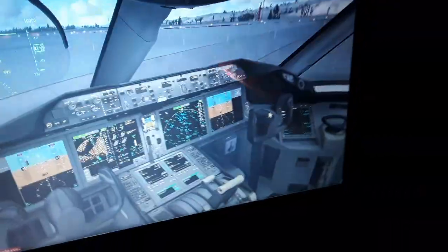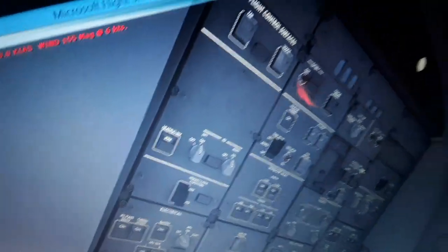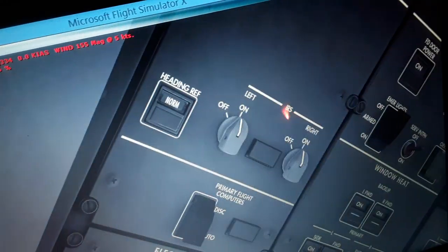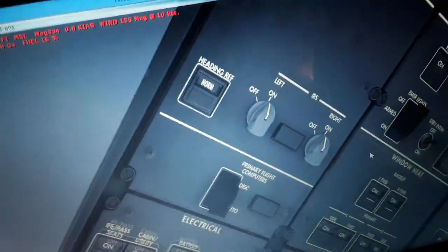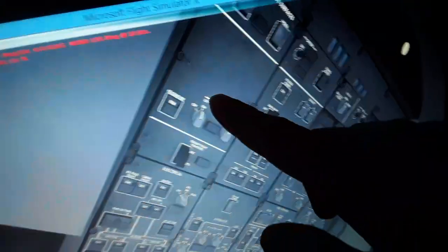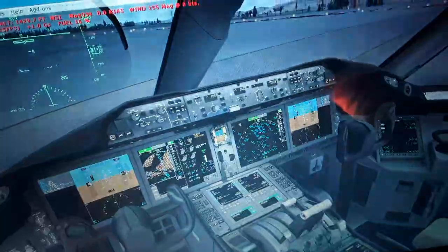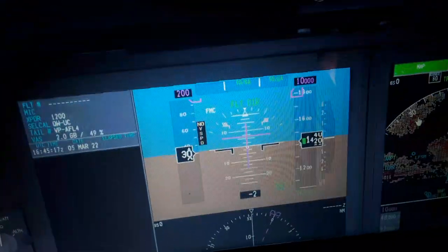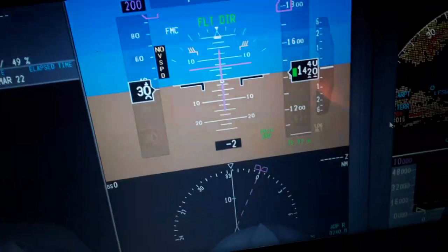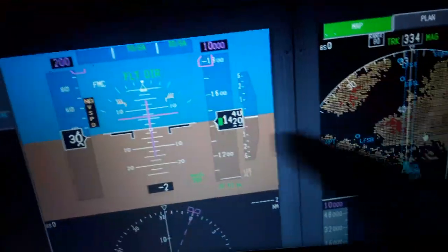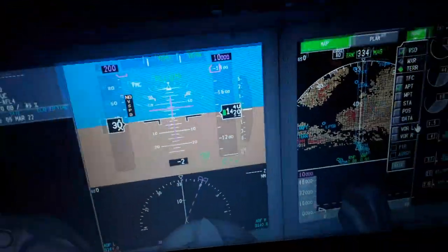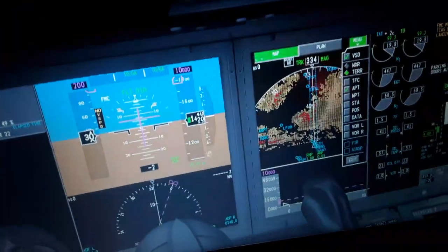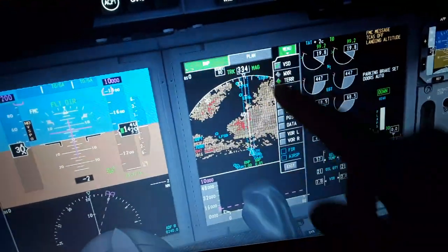And also we have the air data computer over here with the inertial reference system for alignment, GPS receivers, magnetic and geographic north pole, pitot static and pitot dynamic, the airspeed and the altitude of the aircraft from the air data computer, and also the laser gyroscopes for gyroscopic acceleration and deceleration display of the attitude of the aircraft in flight. So we have the terrain and weather reflections over here, the terrain map.